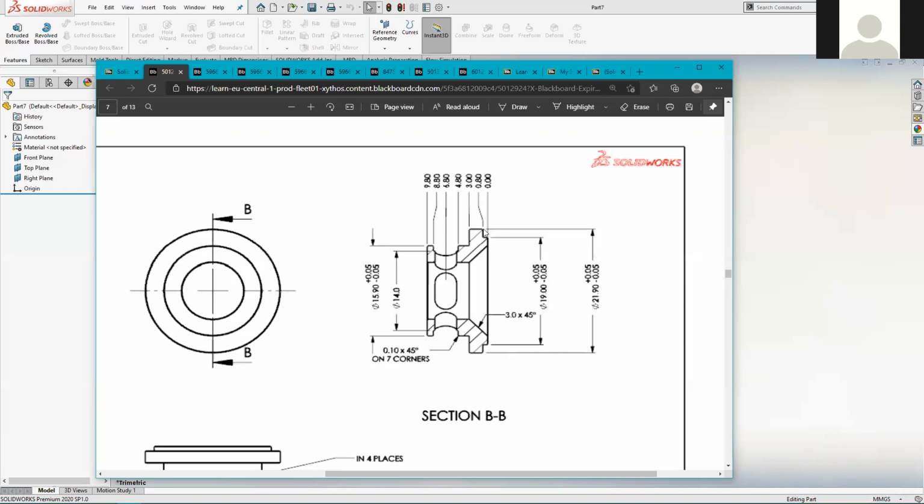So we're going to draw the rough outline of this. Next thing we have to do is decide where the origin's going to be. I'm going to decide to put it here, in line with this initial edge, given that the drawing has used this as a datum edge essentially. It hasn't actually specified that using the correct symbol, but it's essentially taken all the measurements in a horizontal sense from that edge there. So I'm going to put the datum point right there.